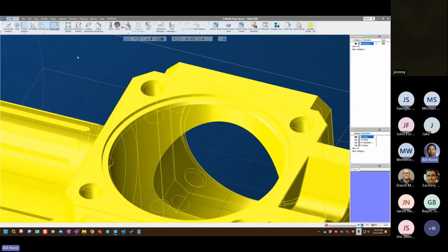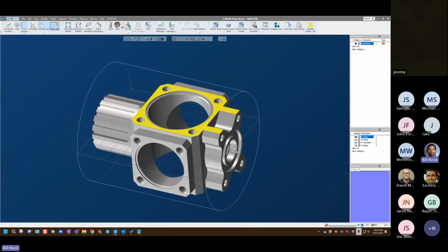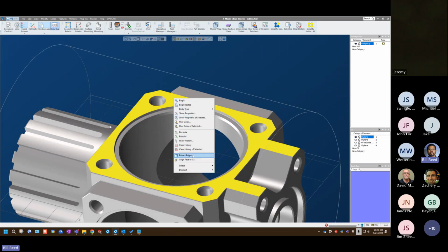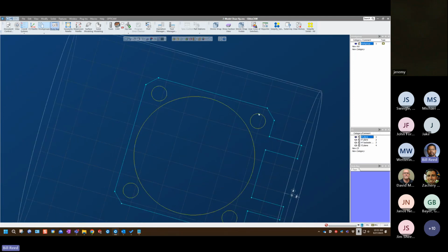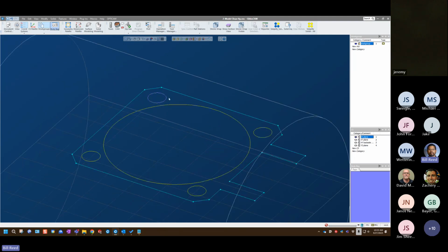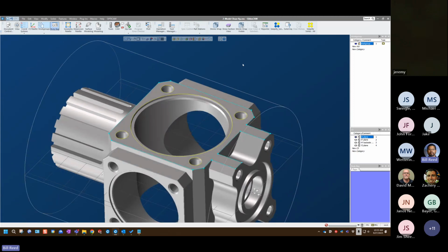So I'm going to click simplify also. And now if I turn on face selection, select this top, right click, extract the edges, and turn off my model, boom, I have nice clean circles. Now that's kind of key on holes, especially because you can't drill a hole from an arc. You can drill it from a circle or a point, but not an arc. So without having to recreate those, this is one way to clean up your model, give you better functionality.